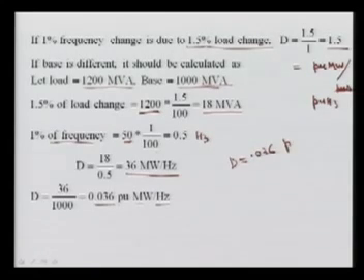0.36 per unit megawatt. Now it is per hertz, I want to write here in the per unit, and for that we have to now multiply it by 50 if your operating frequency is 50. So this value you will multiply here, so you are going to get 0.036 times 50, and it is 1.8 here, that is coming.